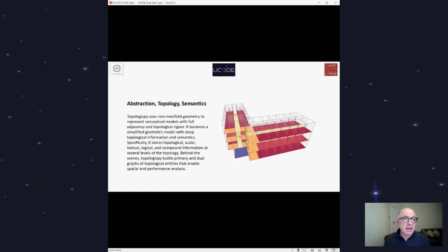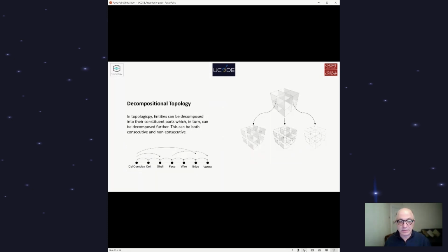I'll show you that. I won't spend a lot of time on this, but basically these are the kinds of things that Topologic is really good at. Simplified geometry. A graph that you can see in the middle here is automatically generated. Every space gets a vertex, and the dictionaries and information that is saved in the space automatically get transferred into the vertices. And once you have a graph, you can find shortest distances, you can traverse it, you can use graph theory to analyze it. All of that is available. And once you get that information and those metrics, you can map them using color coding back onto your 3D model to get really nice visualization of your analysis.